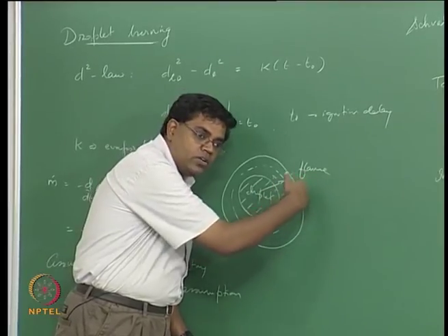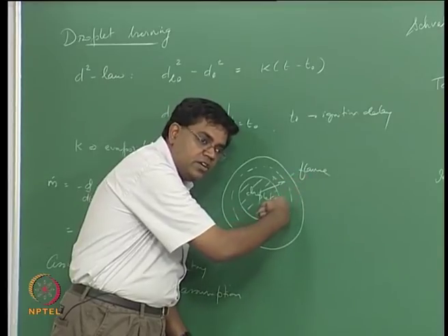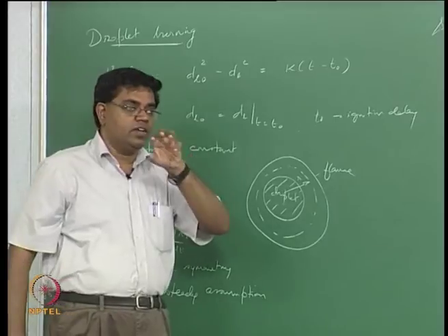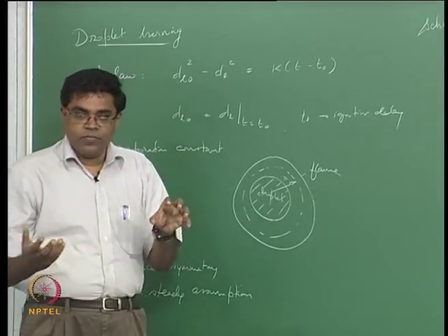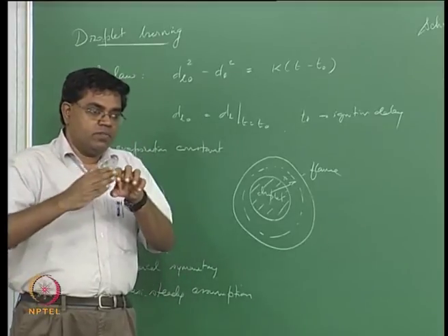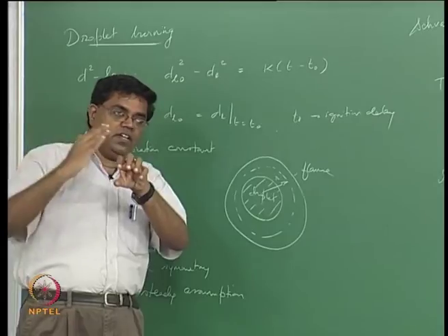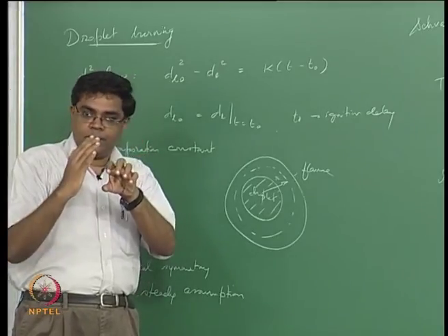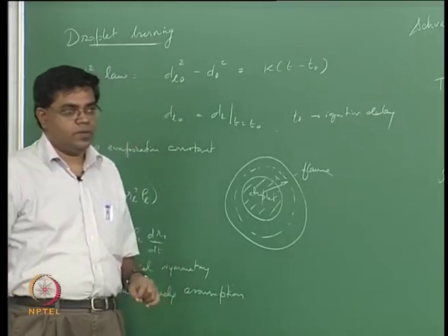But as the water, one of the products, comes back diffusing in, it now condenses, because when methanol exists as methanol, it's quite volatile, right, so it can vaporize, but the temperatures for the combustion are so high, somewhere in here as the water vapor diffuses back in, it can condense, right, and then further in it finds the surface of methanol.